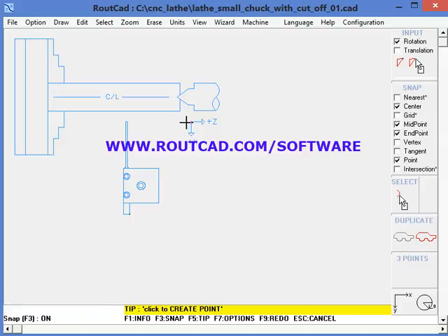At this time, this point is not routed yet. It's in red, which means it could be routed, which means it could be part of the routing sequence, but it's not routed yet. It is, at the moment, a construction element that was made with the keep out of routing unchecked. Now, what we want to do is to move from the origin, the home position of our CNC lathe, which in this case is over here, move to that particular location and go inside to cut that